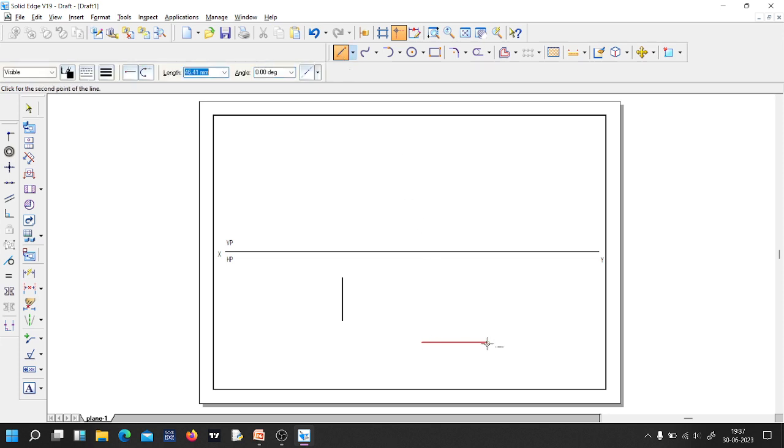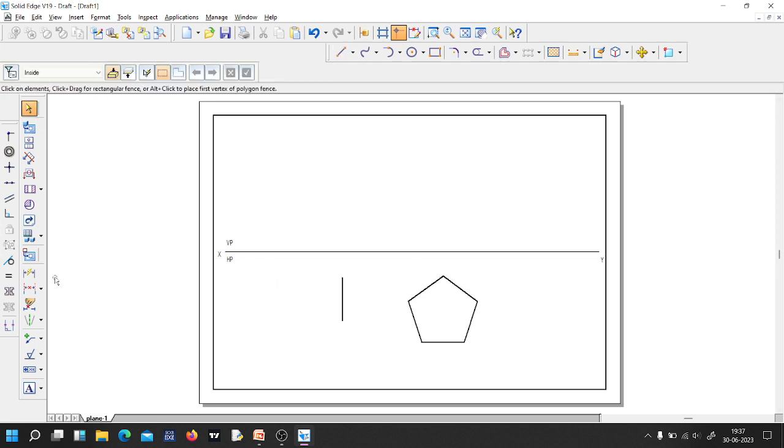First you draw a normal pentagon, placing one edge as horizontal. Now based on the outside angle, you go for calculation, it is 72 here. For the second one you go for 30 and it is 144. Next you go for 30, angle as 216. Then you go for close here.